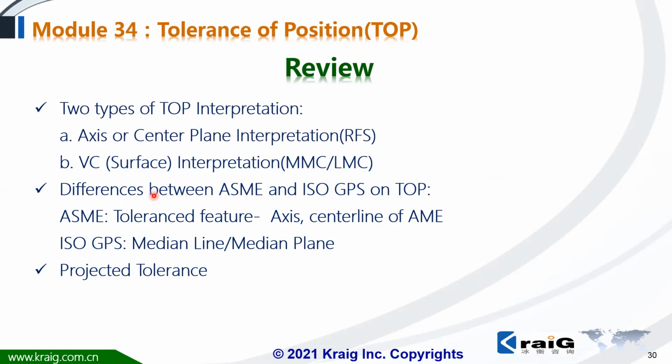We also explained the differences between ASME and ISO GPS on the tolerance feature. In ASME, the tolerance feature is the axis or center plane of the actual mating envelope. In ISO GPS, it is the median line or median plane. We also learned what a projected tolerance zone is.